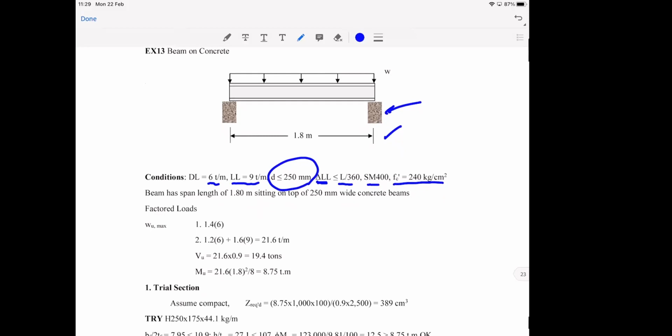All right, so let's say we begin by considering the load combination. And in LRFD, we generally have 1.4 dead load or 1.2 dead load plus 1.6 live load. And if it's not something extremely unusual, this case will always govern.